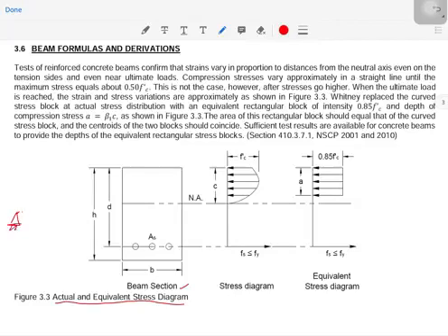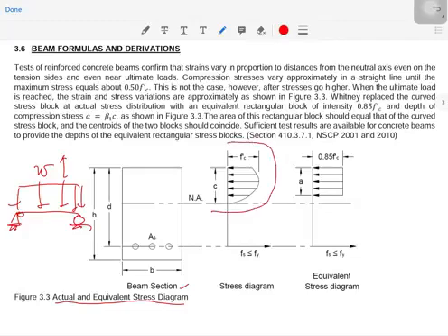If a certain beam, say this simply supported beam, carries certain loads, then as the loads go higher, the strain and stress variations approximately vary into this particular stress diagram here. Now, that is the stress experienced by your beam cross section.